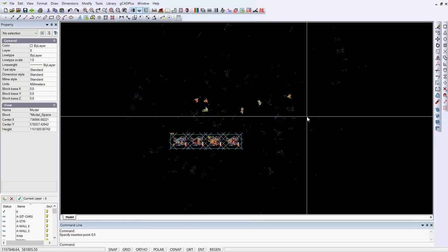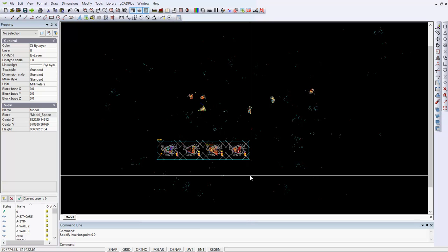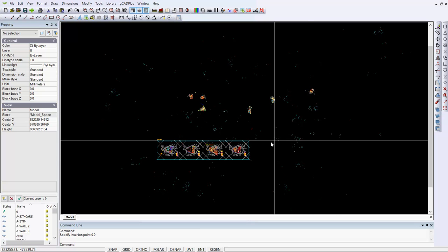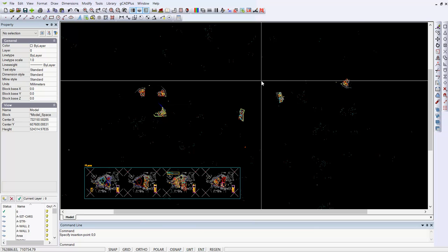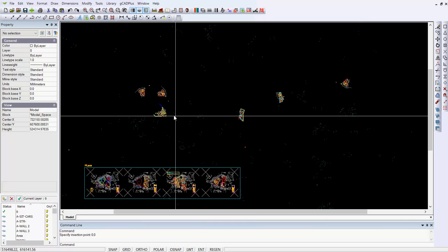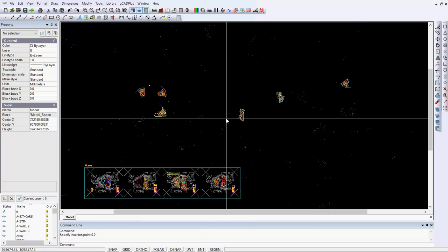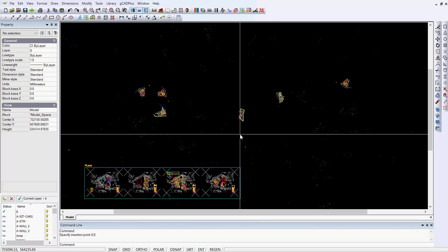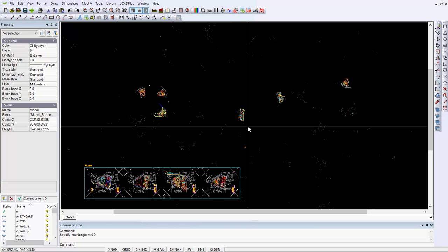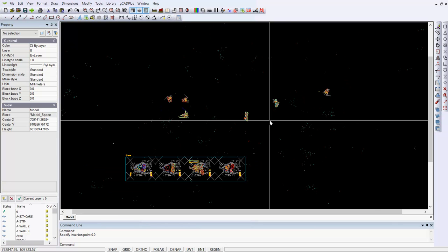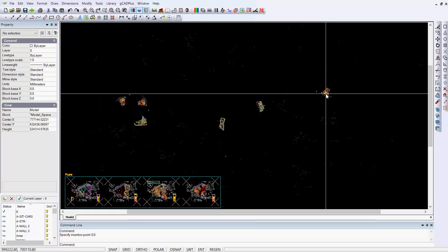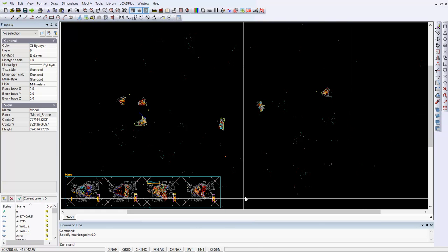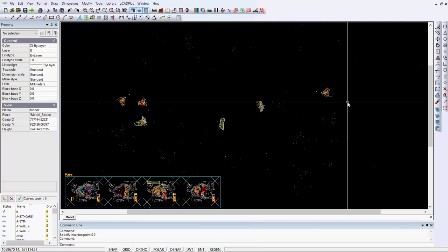You can see now, even though we took a crossing window through there, all of this material outside of the zone we selected has been captured and brought across to another drawing. So you can see the difficulties we face. You might be able to simplify the drawing by exploding each one of these blocks that's outside. Whenever you copy to the clipboard and paste, just use the regen.